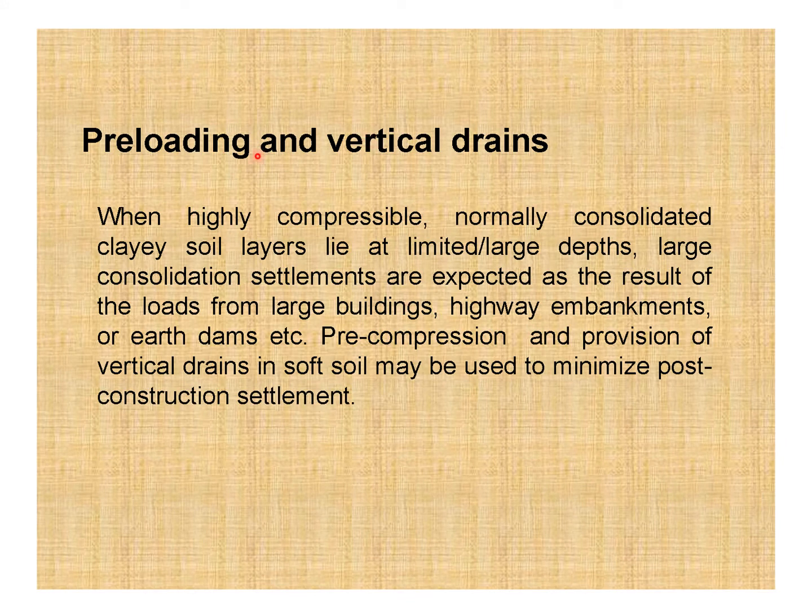Today we are going to discuss preloading and vertical drains. When highly compressible, normally consolidated clay soil layers lie at limited or large depth, large consolidation settlements are expected as the result of the loads from large buildings, highway embankments, or earth dams, etc. Pre-compression and provision of vertical drains in soft soil may be used to minimize post-construction settlement.